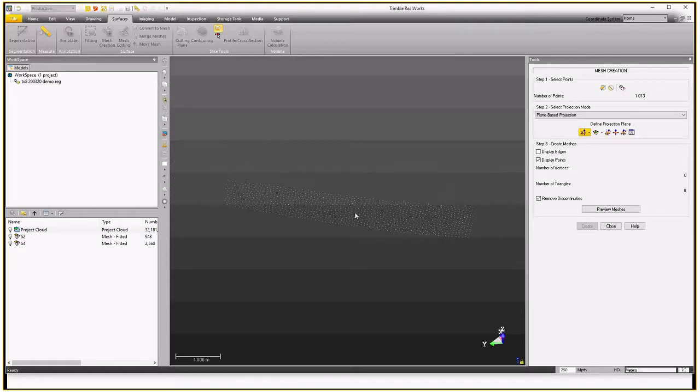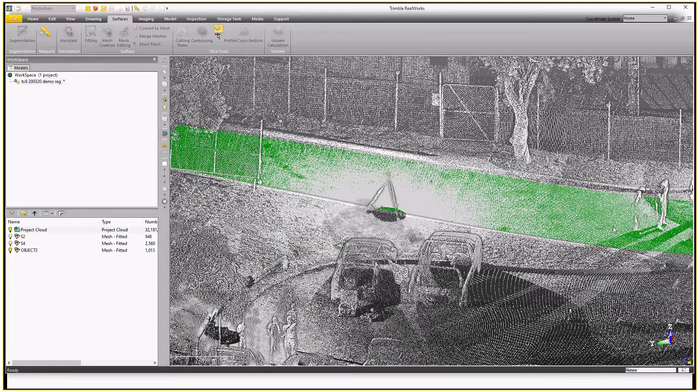And we want our mesh thrown down on this in the Z projection, which is right. So if we hit preview mesh, it's done. Okay, so we've got a nice smooth mesh there, no spikes sticking up in the air or anything gnarly like that. So if we hit create, close. Okay, we've now created our mesh on the ramp down into the car park.